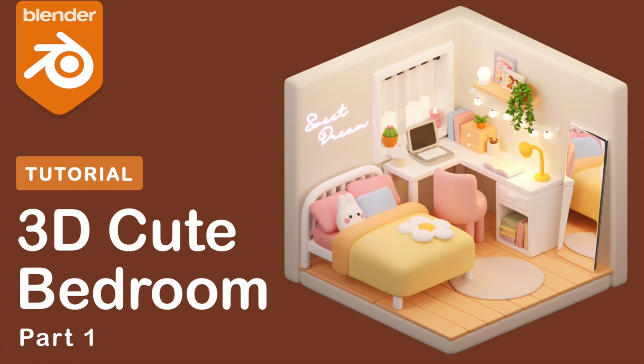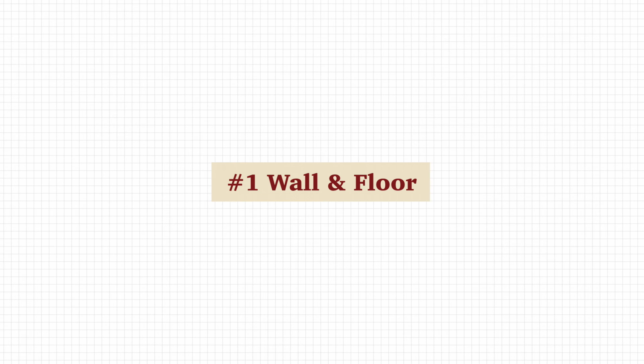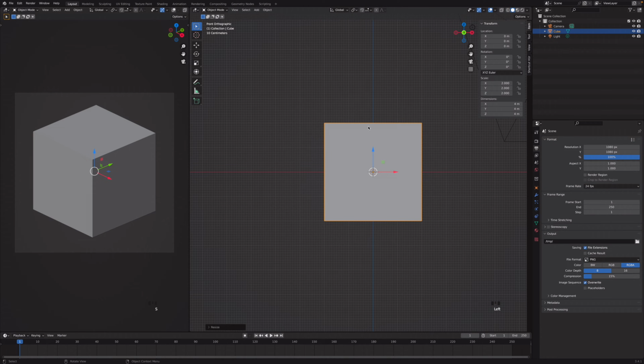Today I'll show you how to make a cute tiny bedroom / study room in Blender. So let's go ahead and get started. I already talked about the setting and how to navigate in Blender in my previous video, so you can go back to check them out. We will start with the default cube. Press S2 to double the size, then move it into the position.